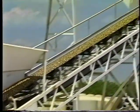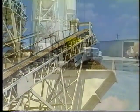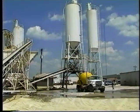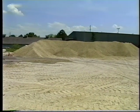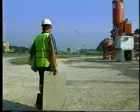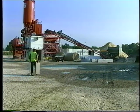All of the given material will be judged based on the results of tests performed on the sample. The sample must accurately represent the material being tested for the test results to be valid. To increase the probability that all the material is properly represented, samples are taken from different parts of the material mass at random locations. As a department inspector, it is your duty to check construction work and materials used on your job to be sure that they meet the standards set by the department.